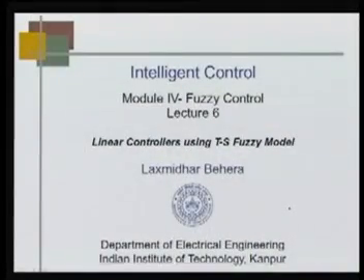This will be lecture 6 on fuzzy control. The topic that we will be discussing today is linear controllers using TS fuzzy model. In the last class we discussed how to design controllers for TS fuzzy model when the input matrix is common for all subsystems. Now we will consider the generic TS fuzzy model and how we design linear controllers for it.